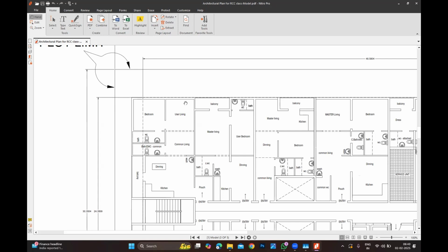Don't ever place the column from the basement. If someone starts placing the column from the basement, you don't have the concept of it and you don't know how to place the column, because it doesn't work. It's very straightforward. In the basement you will have only parking and water drainage. What else? Hardly a storeroom, or an underground water tank. Other than that, you don't have anything in the basement most of the time. Now, what happens if you start the column from the basement? 80% of the columns are going to clash with your apartments.